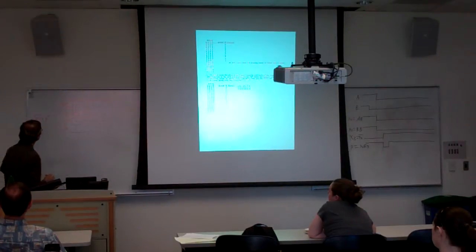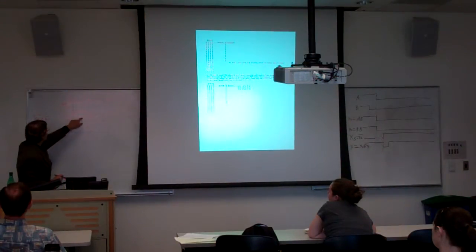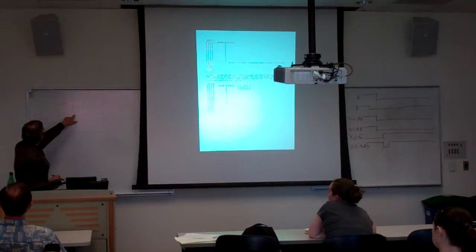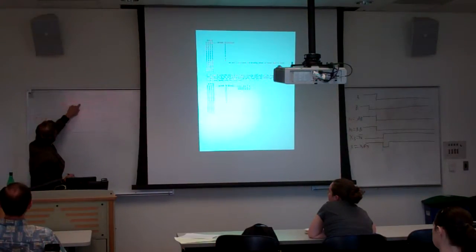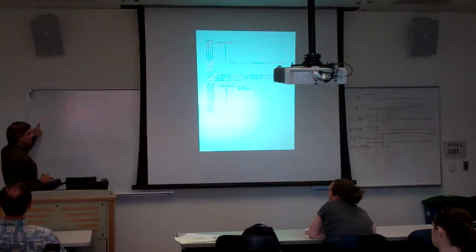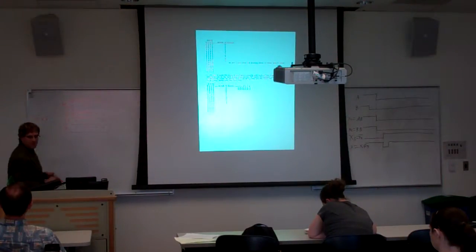Right. So at every point in this rectangle, W is 0. So that's not W. X is 1, so that's X. And Y is 0, so that's Y bar. Z takes on the value 0, 1. So we have a term containing 3 variables. That's going to be a 3-input AND gate that we need to implement it.